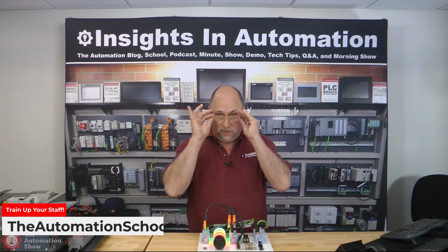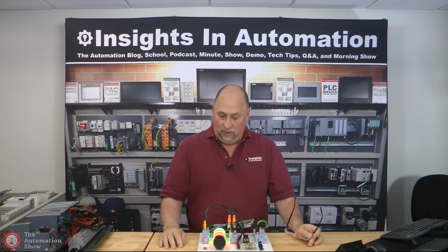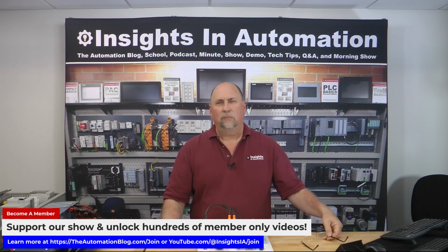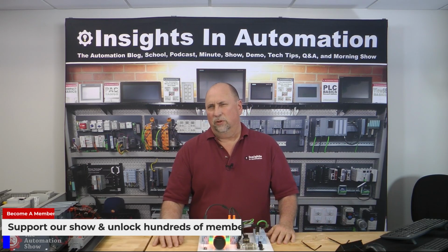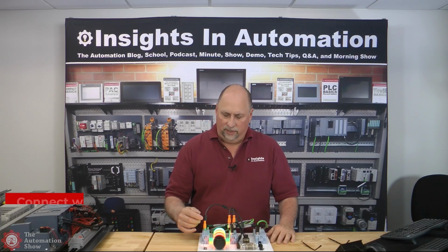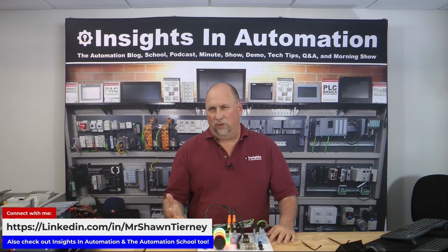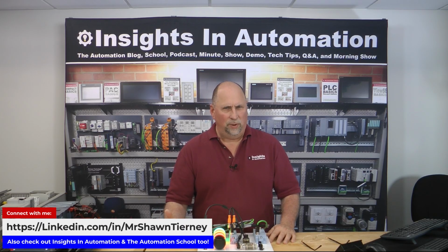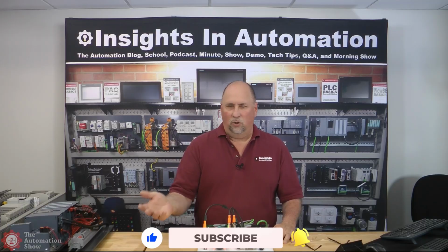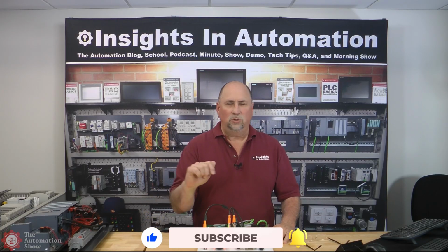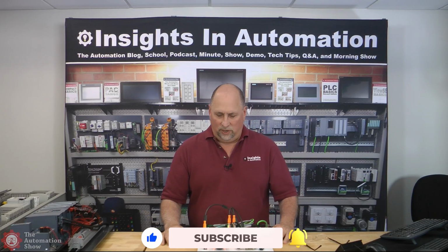And again, this was the first time I've done IO-Link with Siemens. And I know there's different ways of doing it. You don't have to use the PCT tool if you don't want to, but it seems like they really encourage you to do that. And I've got to tell you, once you have that installed, which it should be installed by default with your software when you install it, it was pretty easy to use. Just right-click on the IO-Link card, open up the PCT tool, add your IODD file, and boom.